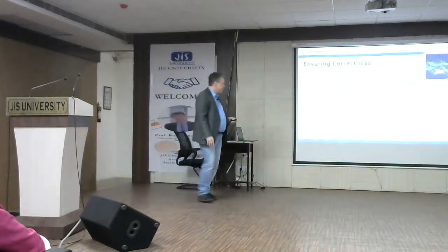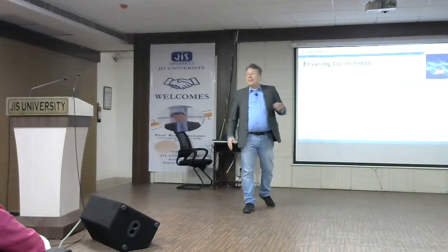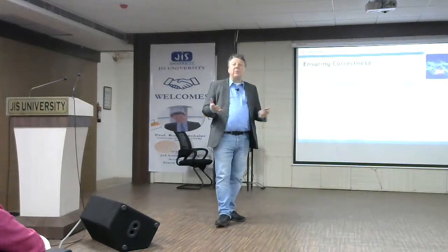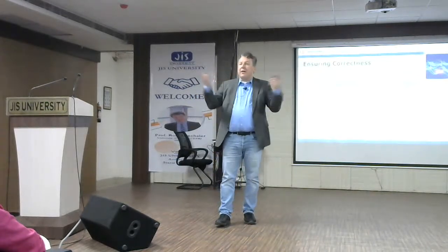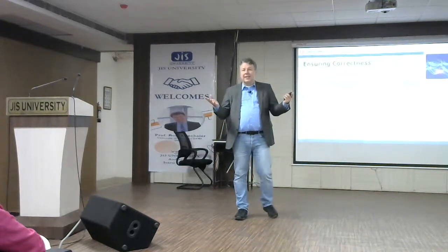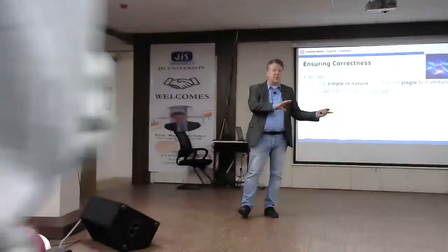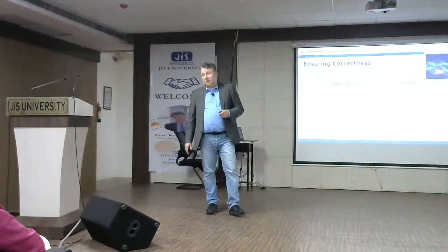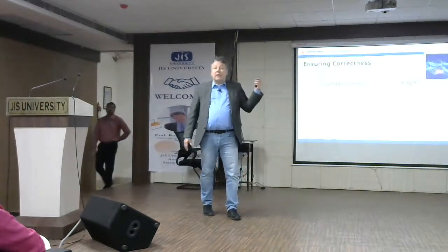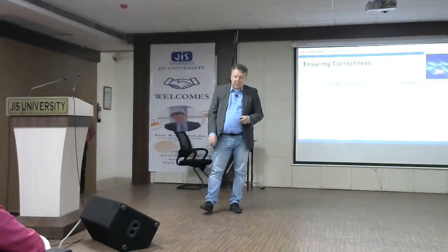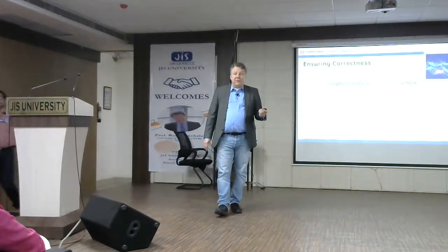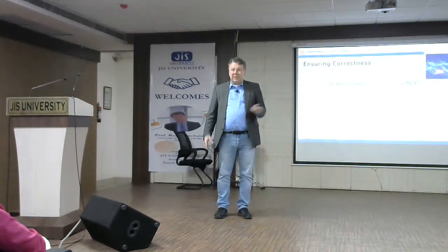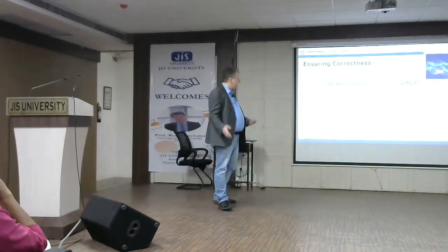So there's the option of having this kind of test vector that you apply. But the difficulty is, even if you apply 1,000 test vectors or 100,000, this is nothing compared to the complexity of the system. So the coverage you get is very low. That's one of the difficulties you have. Nevertheless, as has already been said earlier, you have to do verification. The alternative would be, say, we don't build circuits anymore. But of course you want to build them, and you want to build them as good as possible.